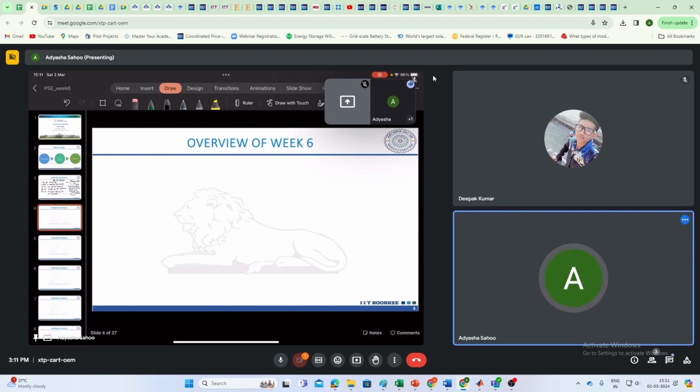Now the stress on the conductor per area, that is stress per unit area, is calculated as the tension acting on the conductor divided by the cross sectional area of the conductor. Tension we measure in kg, and cross sectional area will be in meter square or cm square. From this you can calculate the stress on the conductor per unit area.